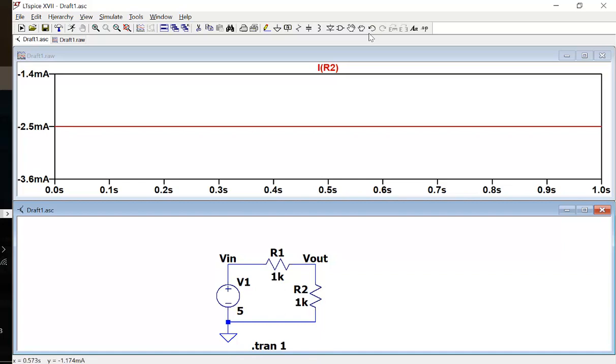Okay, so you can use this hand tool here and take it out. Keep in mind, you've got two hand tools. This hand tool is going to cut the component from the circuit, and you can move it around. But this one will not cut it. It's still here. But now I want to cut it because I want to rotate it. Control R, Control R. All right, and then I'm going to run it again.